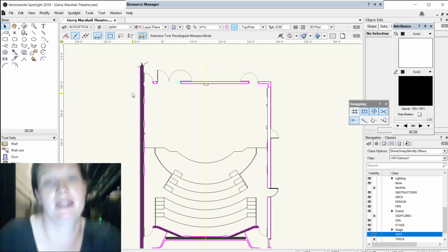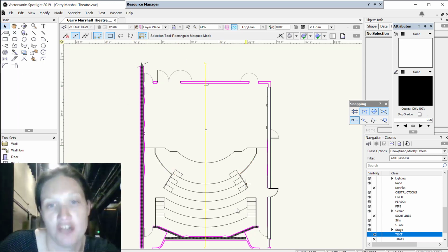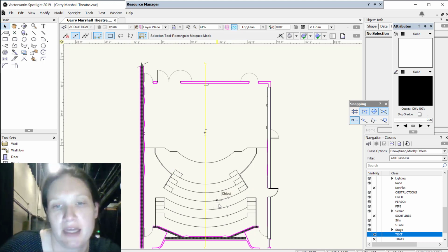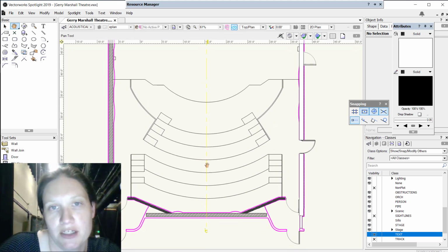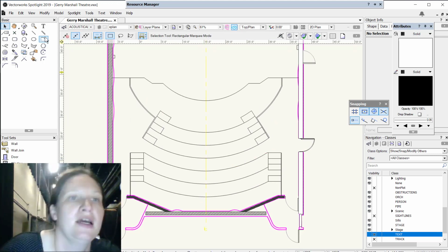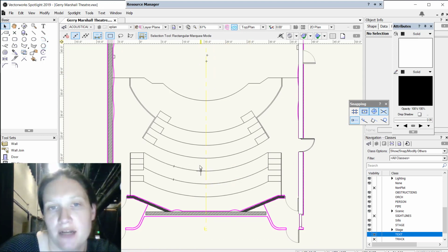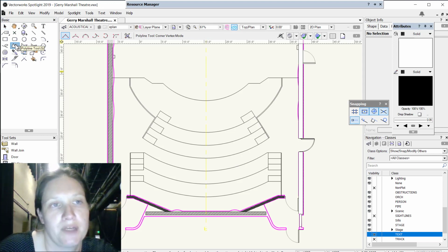Alright, so we're going to use the Polyline tool to trace some of these shapes, okay? It was something I couldn't figure out initially, but I wanted to go back now that I have a lock on it and show you guys how to do it if you haven't already gotten into that business. So the Polyline tool lets us do lines and arcs. You would hit number 5 as your keyboard shortcut to pick it up on your cursor.